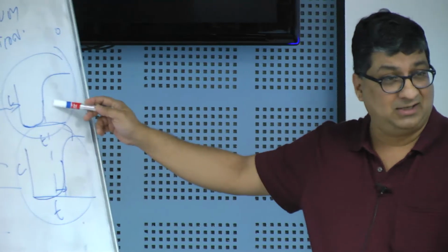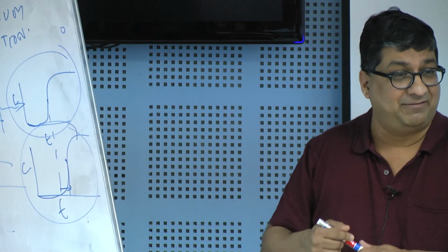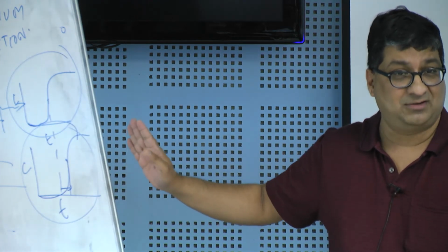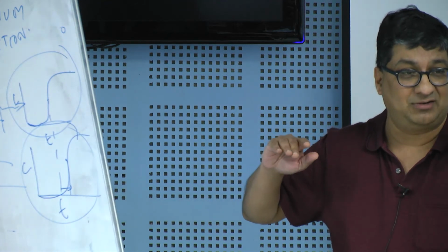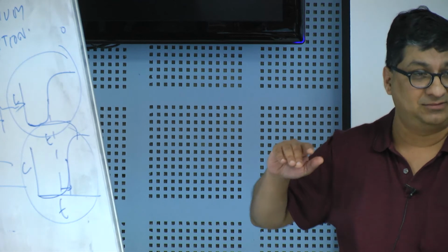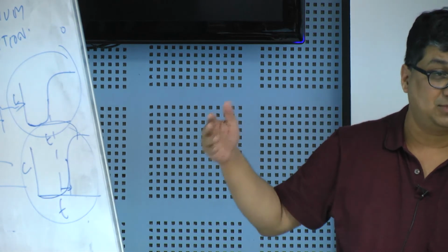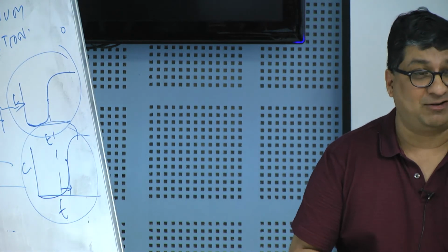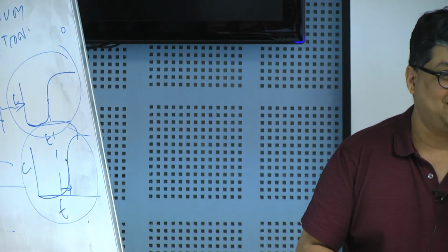If you are interested in a desorption mechanism, where you say, okay, I have some chemical in the solid phase and then I want to remove it, if I were to move it very slowly, my contaminant profile will look like this, right? But if I'm moving very fast, this will shift much onto the other side. So in the desorption, retardation is when I'm generally looking from water to the liquid and then back. If you're strictly doing desorption, then you have to use kinetics to describe it, because that is the dominant process. If it's equilibrium, you're not removing anything, the ratio still stays the same.